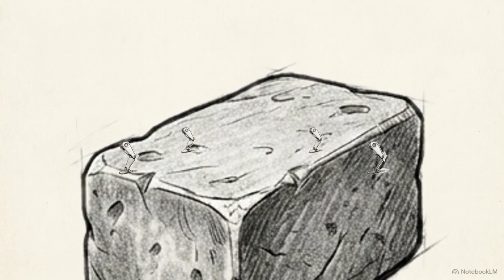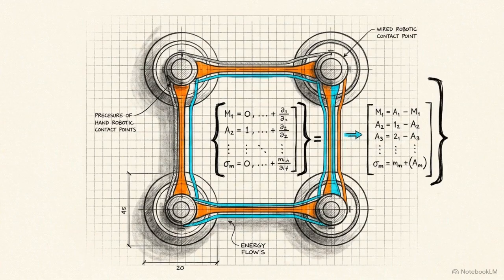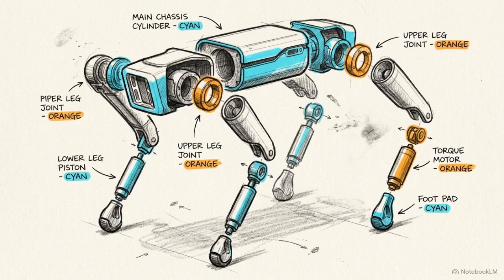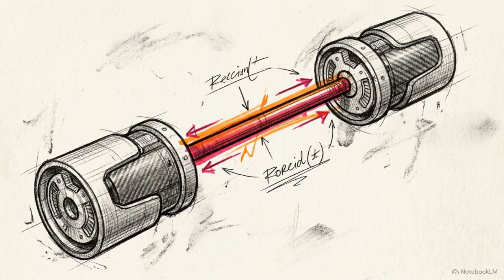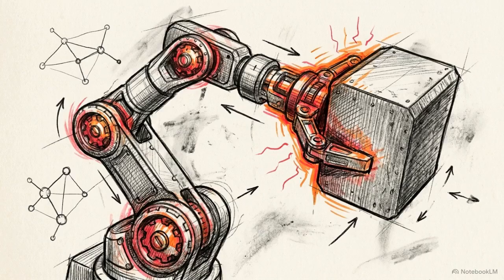That brings us to Bullet physics. It uses a constraint-based matrix solver instead of iterative guessing. Looking at our contact points again, Bullet solves all 4 ground constraints simultaneously. There is no guessing loop, so the compounding errors disappear. Bullet has a drawback for robotics, however. It treats your quadruped as 12 independent bodies, forcing them together as constraints after the physics are calculated. While Bullet handles soft bodies and general physics interactions well, treating a complex 12-degree-of-freedom robot as a series of post-hoc fixes is suboptimal for articulated systems.